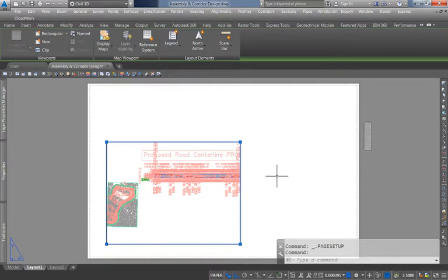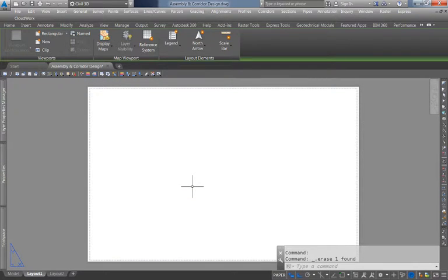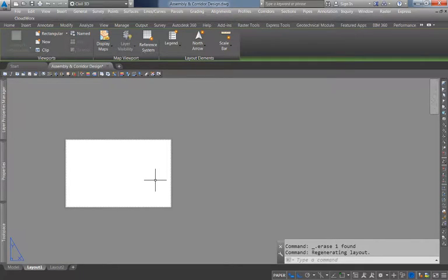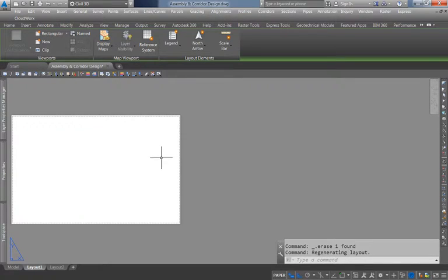So this is our M view window, our model view window, the hole in our paper looking down through the paper into model space. I'm going to just go ahead and get rid of that for now, so I will highlight it and delete it. And then in a lot of cases you're going to have a title block that you'll have to insert here. I'll quickly create a little title block that'll help us keep track of what we're going to plot in